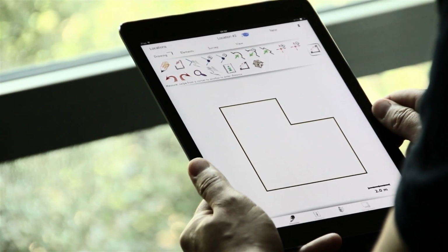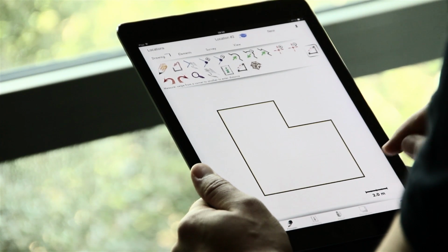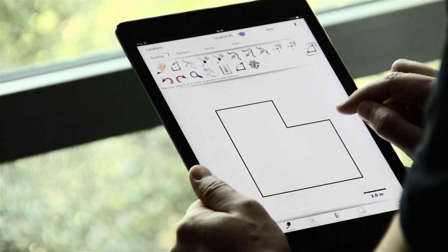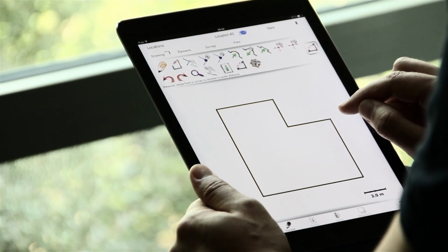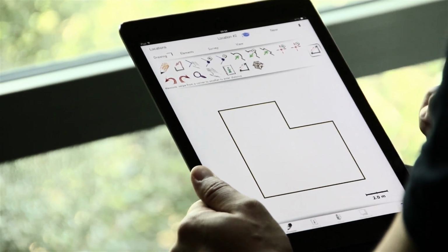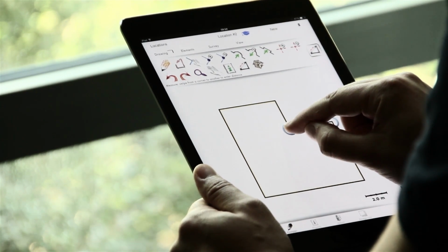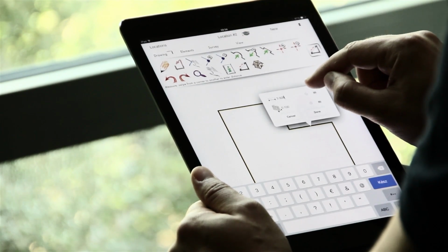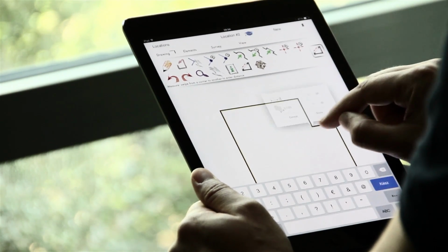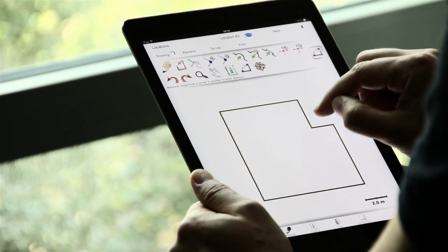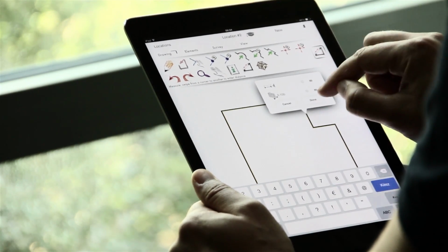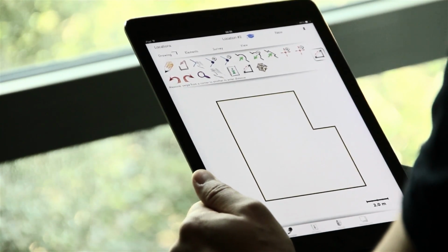Because in OrthoGraph, it's always the ending point of the measurement which is put closer or pushed away, you see. So if you enter a greater value or a smaller one, then the ending point is always modified. Let me demonstrate how that works. Let's go with the third wall, like this. If I add a lesser value here, let's make it 2 meters, then the ending point is pulled closer. Now let's go with the fourth measurement, and it's going to be 4 meters, for instance. Now the ending point is pushed away.